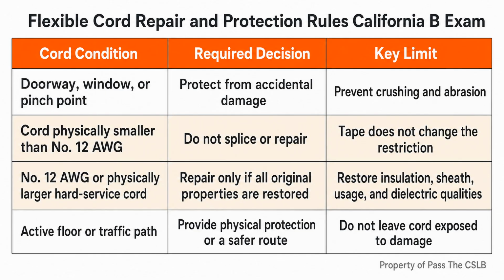I treat the space around electrical equipment the same way I treat an exit path. Available means available now, not after somebody moves 3 things. Disconnecting means also need clear identification and control. Each disconnect must be legibly marked to indicate its purpose, and it must be capable of being locked in the open position. An unlabeled breaker or switch forces a worker to guess what will be de-energized. A disconnect that cannot be secured open undermines the next safety step.